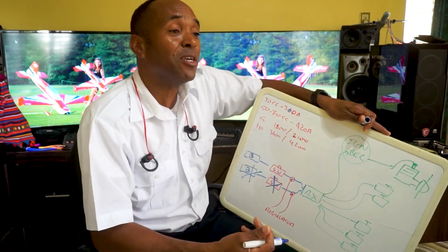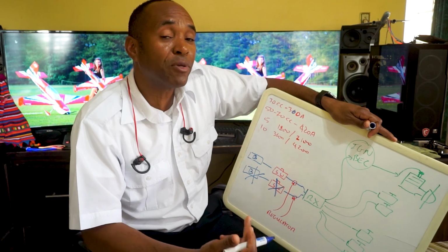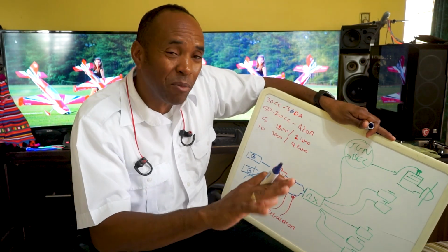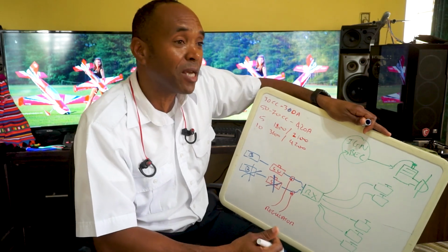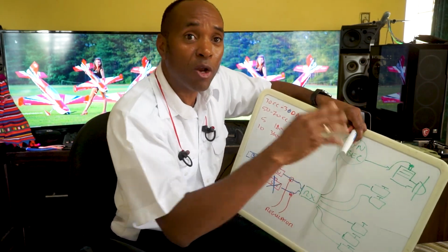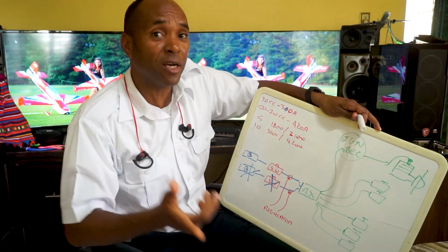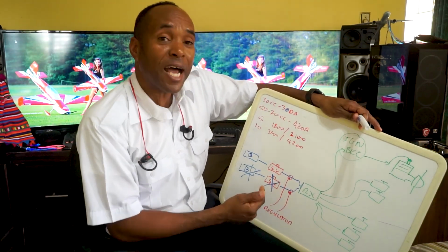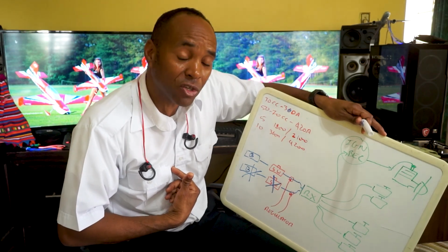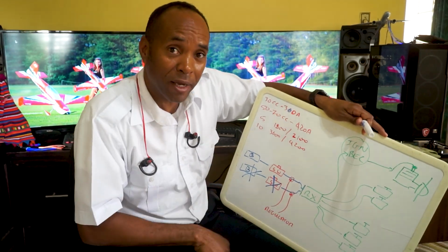For a 50 to 70cc airplane, the peak amps can go up to 20 amps, right? Usually about 15. A big freestyle pilot can push it up to 20 amps. For a 100cc airplane and up, you're talking even higher figures than this. The switches that I choose to buy are rated at 20 amps continuous each, 30 amp spike.